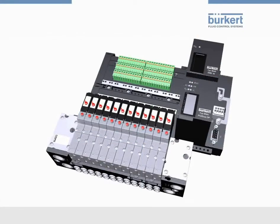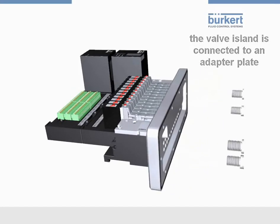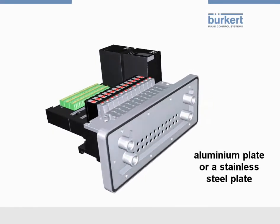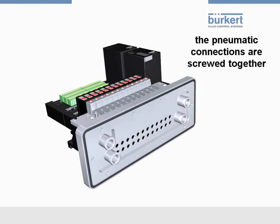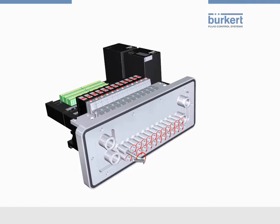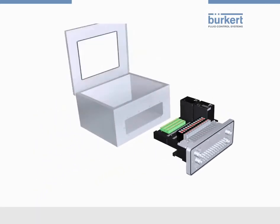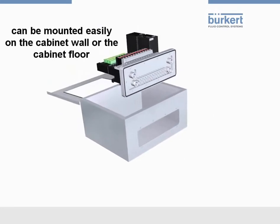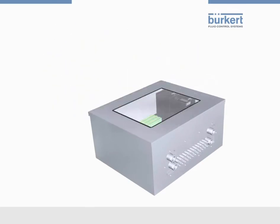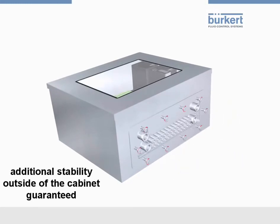How is Airline Quick constructed? At first, the valve island is connected to an adapter plate. Depending on the demand concerning durability and cleanability, you can use either an aluminium plate or a stainless steel plate. The pneumatic connections are screwed together between the adapter plate and the valve island. The connections are available in stainless steel or nickel-plated brass. Afterwards, Airline can be mounted easily on the control cabinet wall or the control cabinet floor. Lastly, a metal plate mounted on the outside of the control cabinet guarantees additional stability.